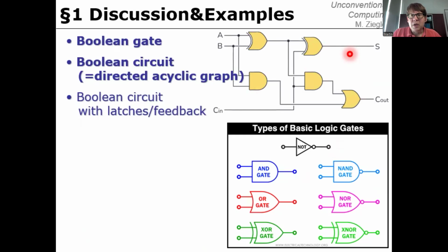This one adds two bits, and if we want to add n bits, we can do that by repeatedly adding 2 bits, but following the carry, and the next stage, input that output of the carry to the next stage, and thus we can iterate this. This is a directed acyclic graph. The edges here are implicitly directed from left to right. This is the way the signal is progressing. And there are no cycles, right? There are no loops here. Otherwise, there's a possibility of a possible inconsistency.